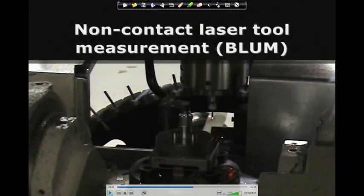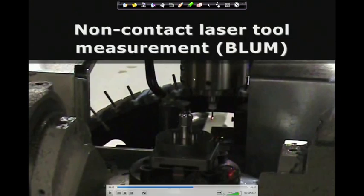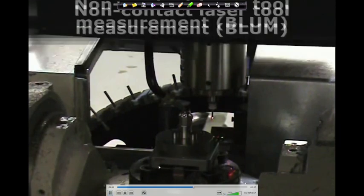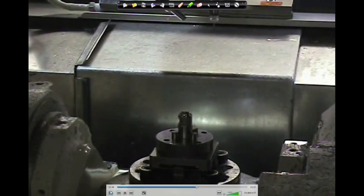So, now once the operation is over, you have to confirm whether the required dimension has been machined or not. So, this is the non-contact tool measurement sensor. This particular sensor will sense and measure the dimension of this particular machined component, and once it is confirmed, then only it will go to the next part. That was done for measurement of the status of the cutting tool.